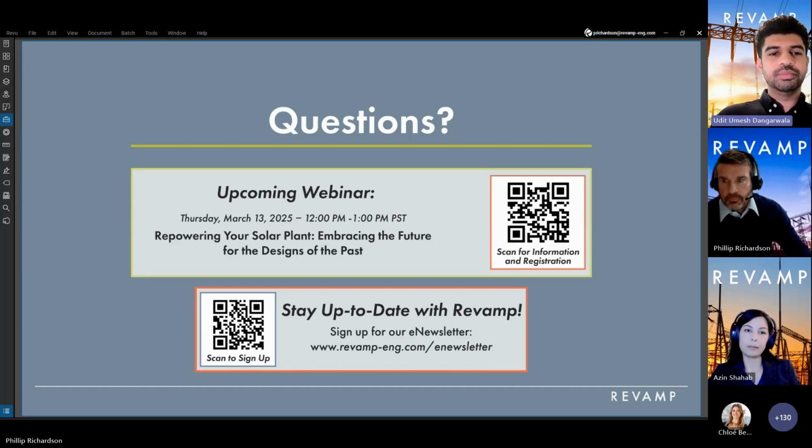In any case, the pre-construction or desktop version that we perform is just a very high-level indicative study because the harmonics in the field get added vectorially. So there's still a lot of estimation that goes into this study. However, if a filter circuit design needs to be prepared before construction, then we do recommend using software like PSCAD that allows us to account for these things and model them more accurately.